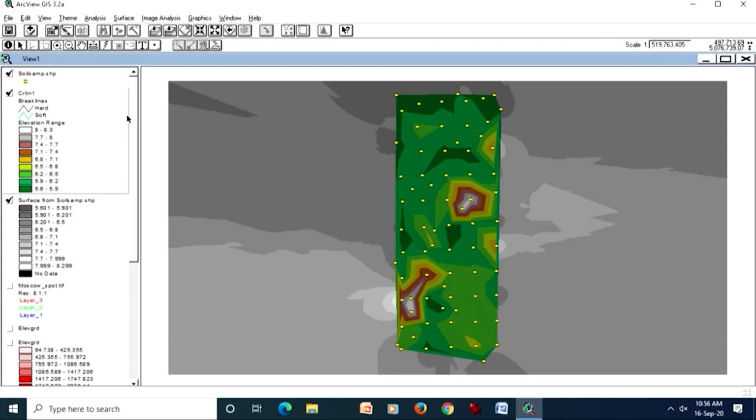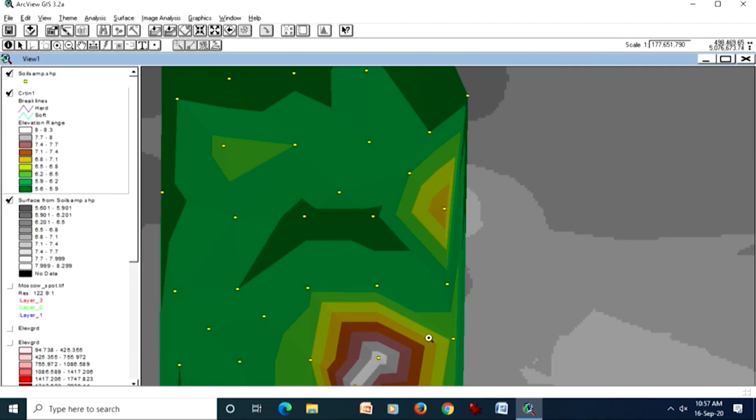Each mass point, each point is used to create a triangle or a facet; rather than calling it a triangle we can call it a facet. Even in this case, like here, if you see, this is one point, this is one point, and maybe a little lower. So here no extrapolation, this point, this point, this point has been used to create a triangle. Recall our Delaunay theorem, which says that a circle should be drawn in a manner that only 3 points it should connect, not any more, and then that triangle is formed. So this is how these facets are formed.